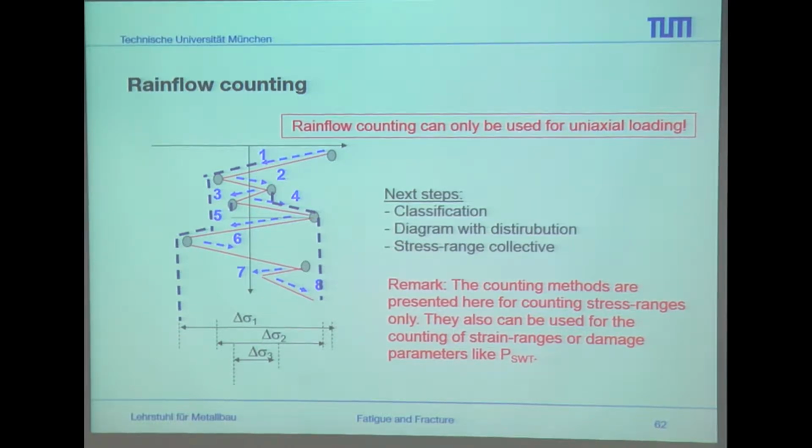But for the system, for the accumulation or the counting of the closed hysteresis, we get no information there. So at the end, we have the information from a signal which goes from here to here to here. So this is the stress range. Also, due to the information about the classes, we get the information about the mean value, which is of course related to the mean value from this class to this class. And we also get the information about a falling hysteresis or a rising hysteresis.